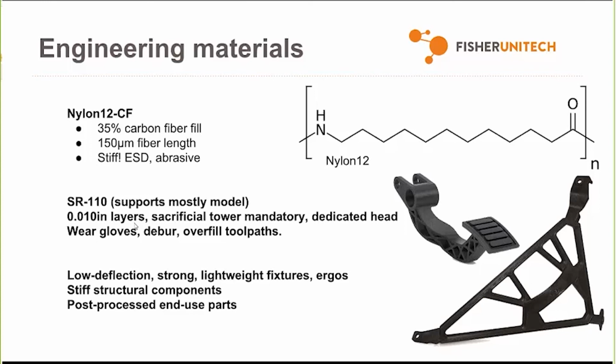Right, so as far as applications, did I mention that this stuff is stiff? It has twice the flexural strength of Nylon 12, but the stiffness is an order of magnitude higher. Nylon 12 CF does build solid by default, like if you use GrabCAD Print, but I think that its greatest strength, pardon the pun, is when you print it with a sparse honeycomb infill. You basically get a very, very strong but very lightweight part.